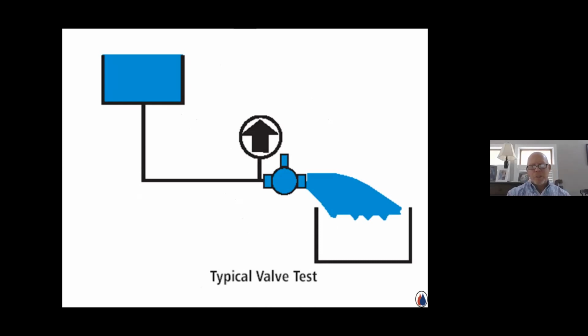And this is a very good visual, but this is how they actually come up with the testing of these valves. So they have this tub of water, if you will. It maintains a constant level, 2.3 feet above the valve inlet, which is a 1 pound inlet pressure sitting right here. 2.31 feet is 1 PSI. The water that passes through this valve is draining into this open tub. So there's no pressure drop, no resistance on the outlet of the valve. So it's just straight a 1 pound pressure drop across.